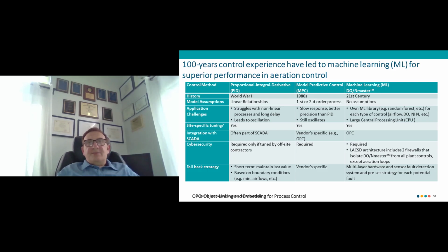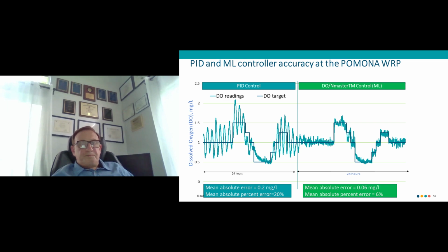Each of the discussed methods requires initial tuning. However, unlike PID, the MPC and ML methods can have self-calibrating features, so after initial tuning is completed, the system may operate indefinitely even if external conditions change.